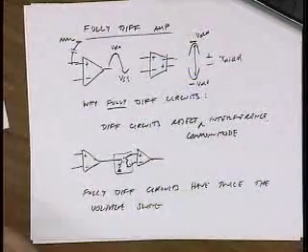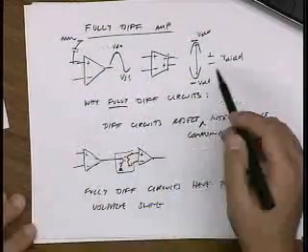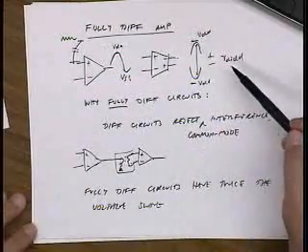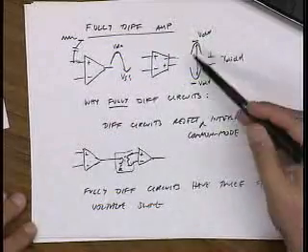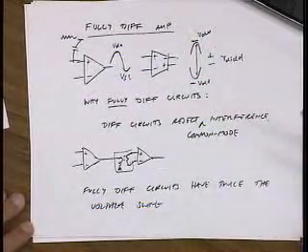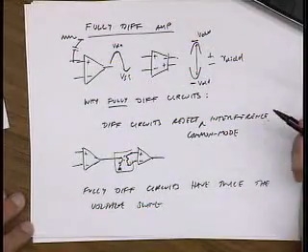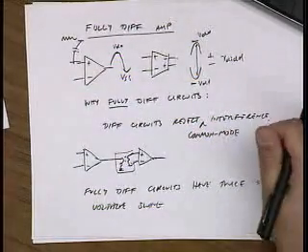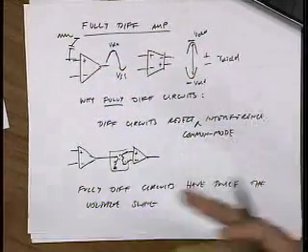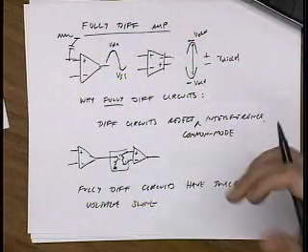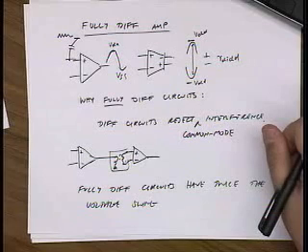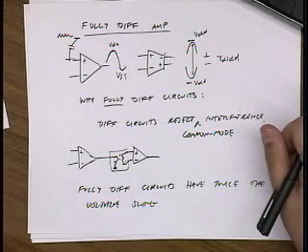And that's, of course, very important because the signal-to-noise ratio at the output goes like the voltage squared. So by going differential, we actually get a 4x benefit. Of course, the noise goes up too because we're differential, but hopefully the noises will add uncorrelated, so we end up getting an SNR benefit in going differential.